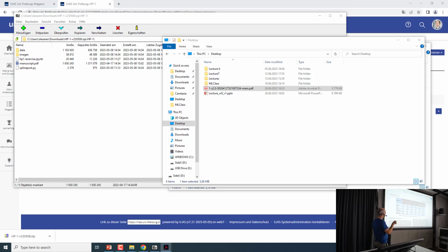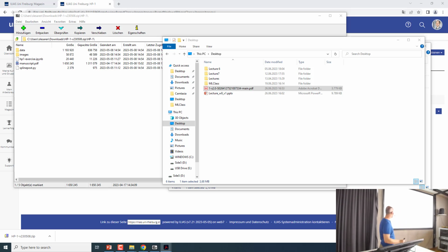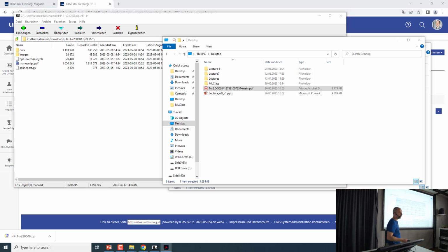So what they wanted to have, what is predicted by neural network, like they wanted to have Poisson ratio minus 0.3 and Young modulus of 3, and what they get, oh no, this is what they generated, sorry. And what they actually had, if you run on the same structures, finite elements models, you will get minus 0.2, depending like from minus 0.2 or minus 0.27 and so on. And Young modulus will also change a bit. This is not so big difference. In this case, probably they pick one of the best samples. And here you have the error on average 15%, and it's quite good.